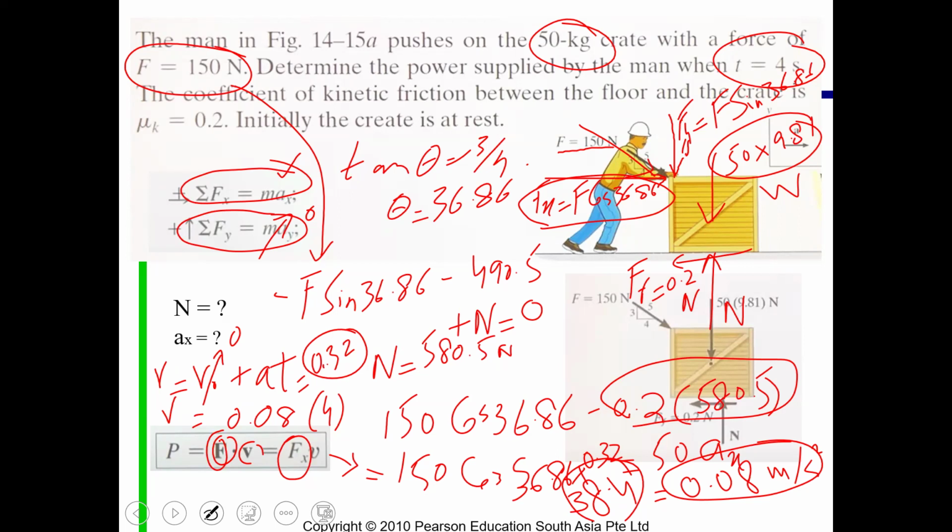This is a very good question, but remember that friction will not come into play again for the power. It has already been used in the dynamics equation when you calculated the acceleration. So velocity already has this reduced effect. If you skipped it, the acceleration would be higher, and when you calculate velocity, the velocity would be higher. So the friction effect of reducing acceleration and velocity is already in the velocity, and you don't need to include it again in the force. Make sense? Yes, I got it.